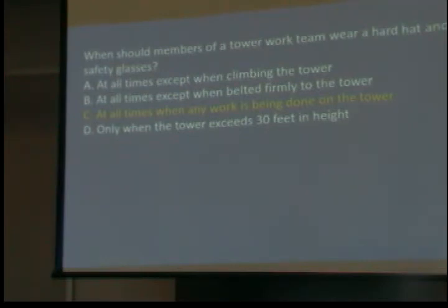If a bolt gets dropped, you're okay. But anything very heavy is going right through that hard hat. It doesn't matter, nothing stops it. If you're working up on or at the bottom of a tower, there is nothing that approaches the value of situational awareness.